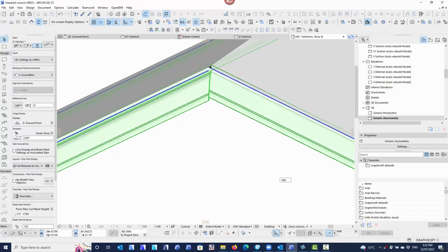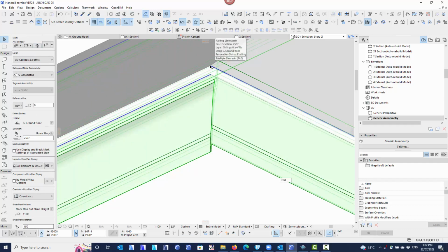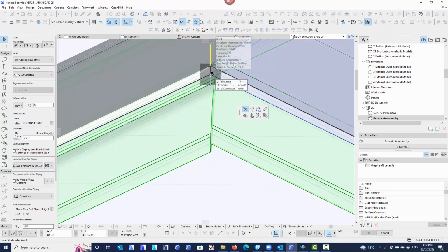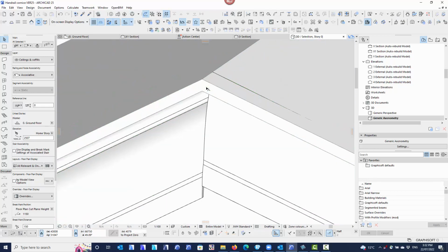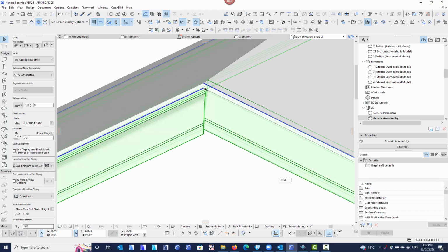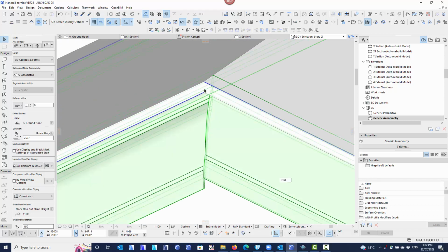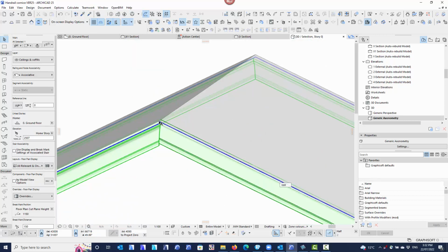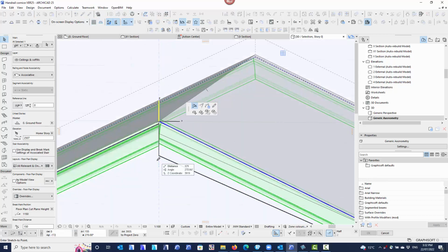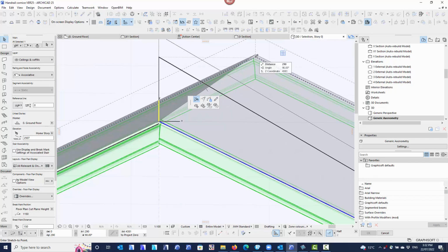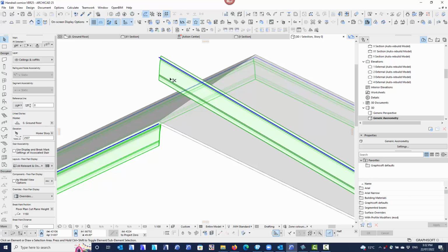Unfortunately, you can't tell it not to associate. You have to simply drag that node and drag the node and do that. I say that forces it to unassociate. Because I've dragged it vertically onto itself, it's going to actually say no. Because I've dragged it to there, it's actually automatically going to associate to that point. What I need to do is I need to drag it vertical, lock it with the shift key, and then link it to something else that's the same height. Oops, I missed. Try that again.